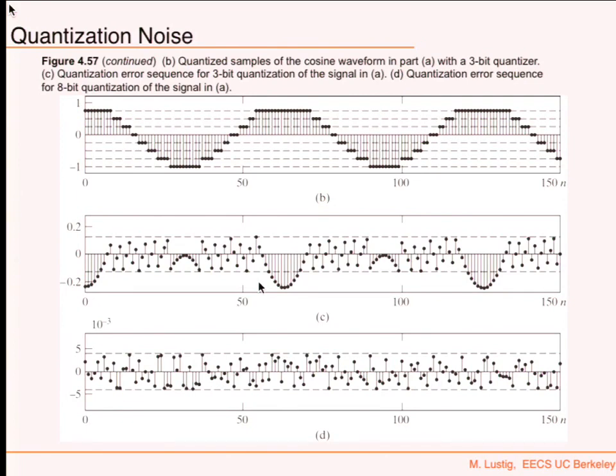You get more correlated errors; they're not going to be as uncorrelated. But if the quantization steps are small, that will be fine, because the error will be broken into smaller parts, which are more random. So you maybe need a little better bit accuracy. But this model works pretty well when we're talking about more than 6 bits, at Nyquist rates and even above Nyquist rates. It's not perfect in this case, but it's still not too bad.